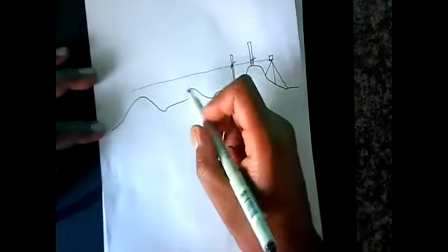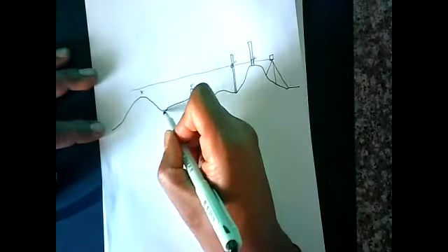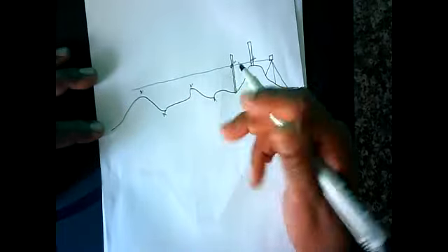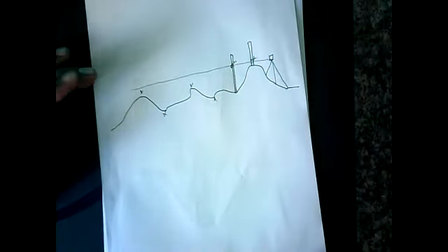All right, now, if these are all the spot levels, what is our starting point? Where do we start? Start there, start there, start there. Which one is it? We need to find an average. That's why this method is called the grid average method. So we've got a grid, we're going to find the average. And let's do that particular example. How do we find the average of our spot levels?